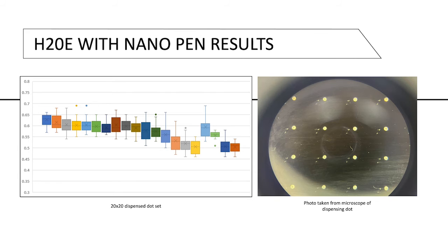At first we suspected this was due to silver agglomerating in the needle tip. Now that can happen not only because of needle type, but also from high back pressure. We typically suggest low pressure of only about 15 psi during dispensing applications.